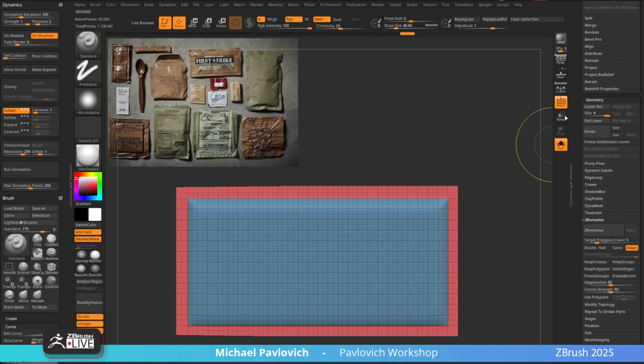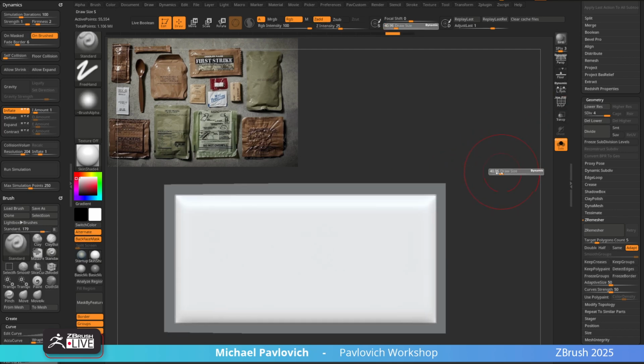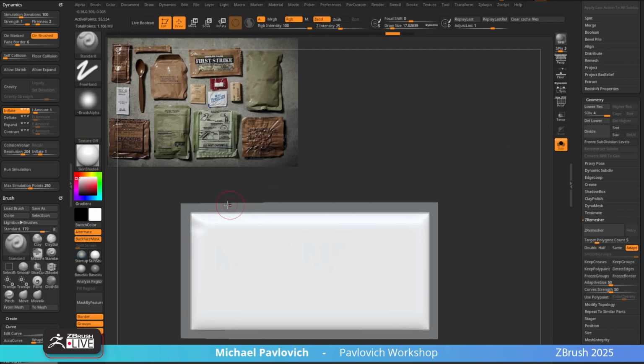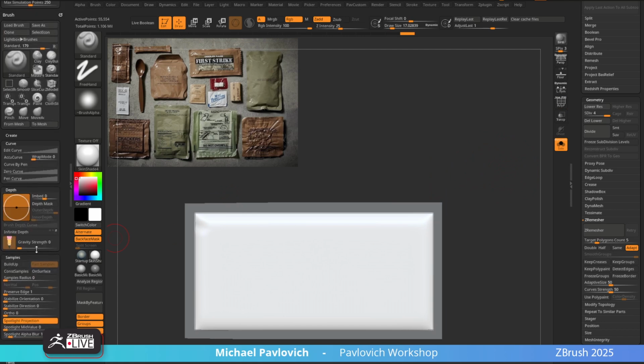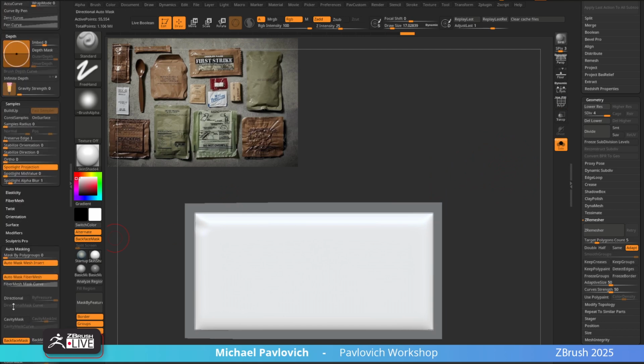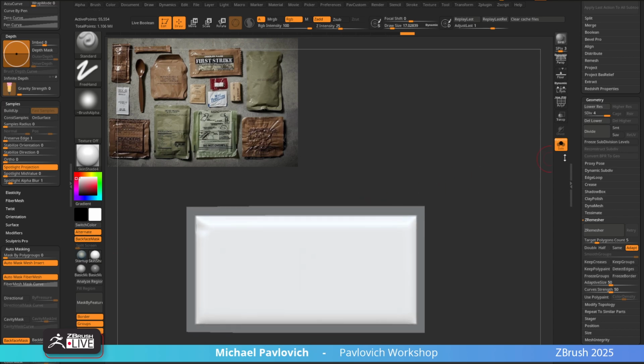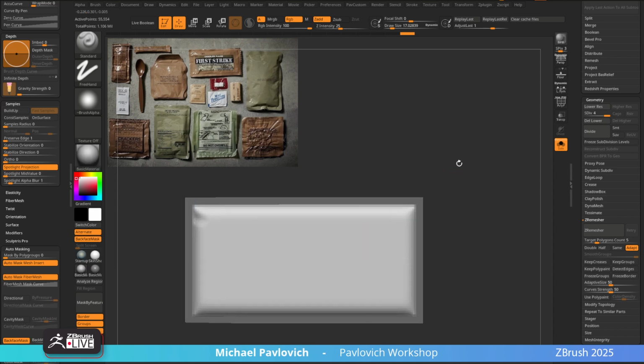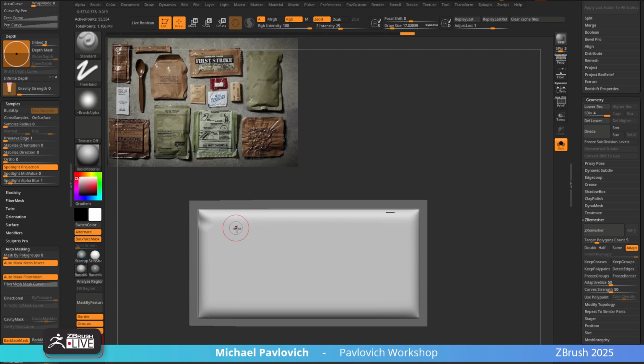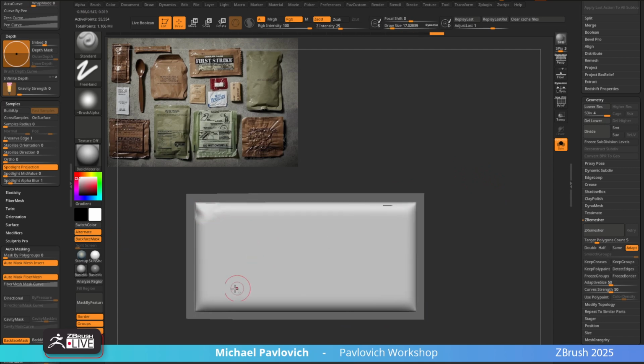So now, again, we have this center part masked. We can go through here and we'll just do a quick pass here. Let me see, our standard brush, auto masking is, spotlight projection on, backface masking is on. So let's go ahead and switch over to like a matte cap gray or whatever. And then go through here. Now we're just sculpting wrinkles. If you want to go lower, you can. Just get some primary forms going.